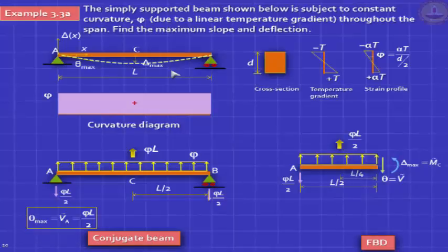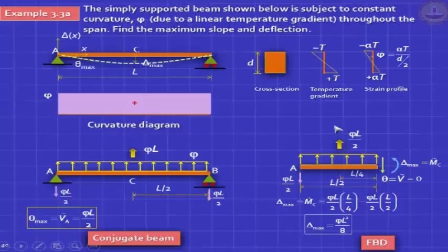And you can calculate that. You know the bending moment in a simply supported beam subject to UDL is qL squared by 8. But you can use the same thing here and you get the same answer. Instead of q, you put 5. That's all. You cracked it, you got the answer.